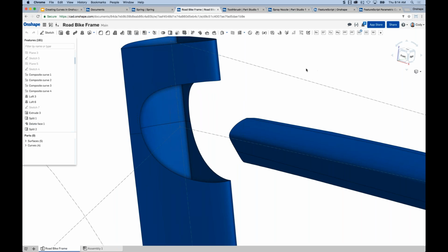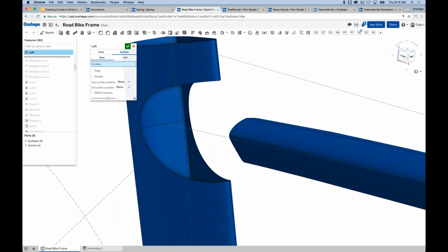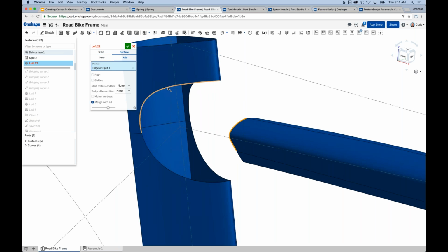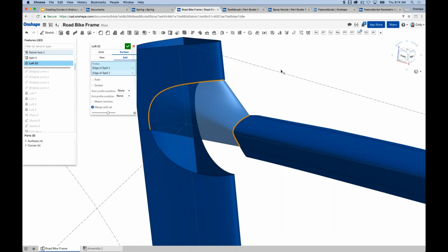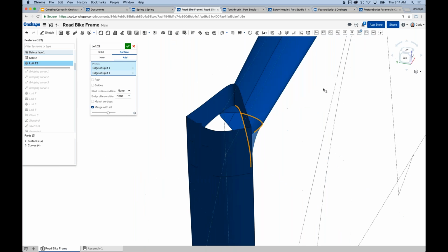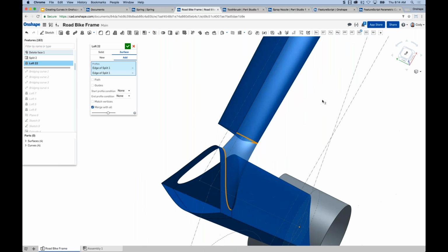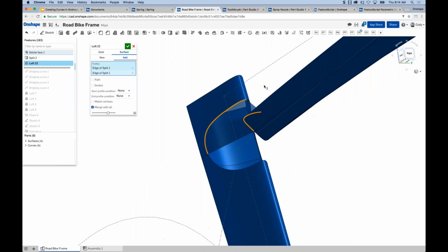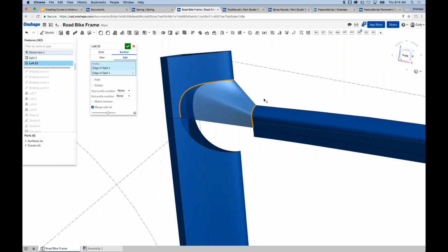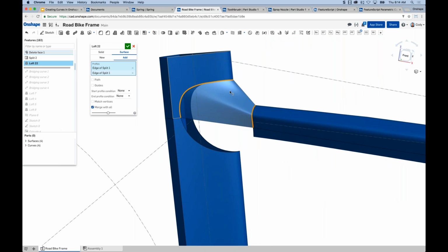But if all I do is just loft, and I select my surface and I select those edges, I'm going to get this sharp transition between them, right? I will get a loft, but it's not smooth, and matching those surrounding contours. It's certainly not the smooth transition that I'm out to get. You can see basically a sharp corner here, and I really want a smooth transition.